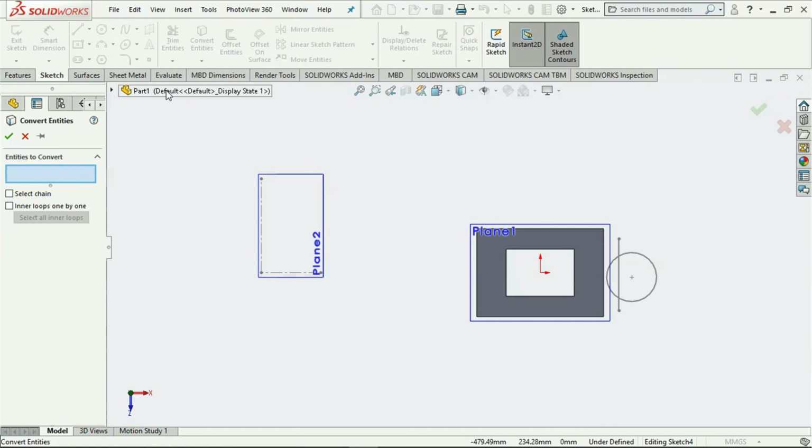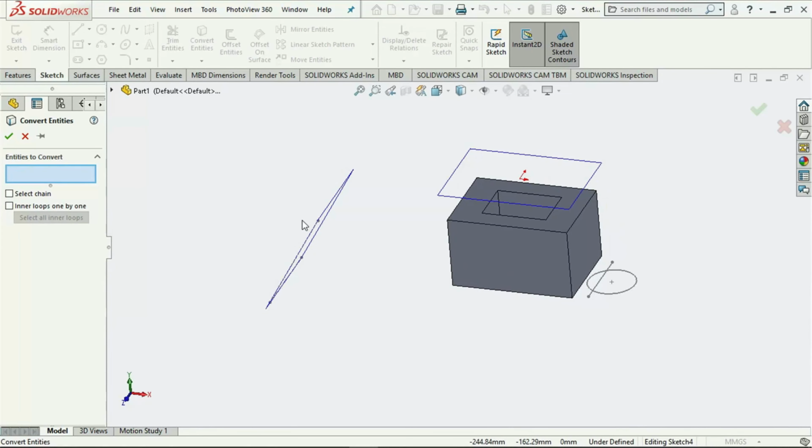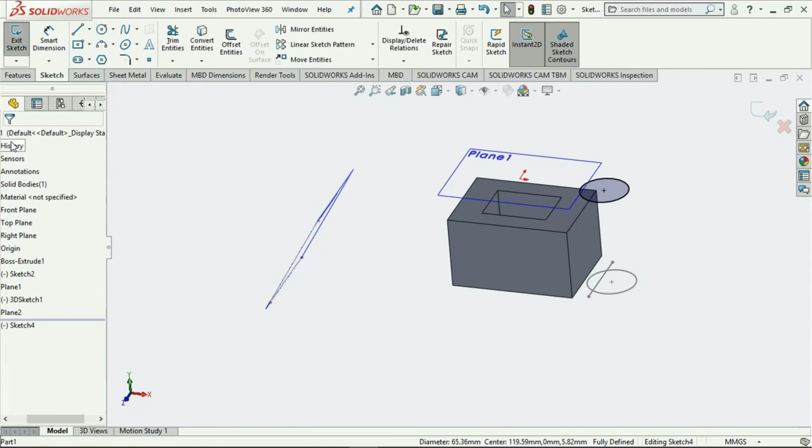Now you notice that I haven't picked a common tool to sketch with. So what I do is I'll just rotate this to look for the sketch I want to convert, and then I click on this, right, and I say check. Now what do you notice? You notice that it's replicated this sketch to this active plane. Now this tool isn't a copy tool, but it serves like a project and then convert tool.